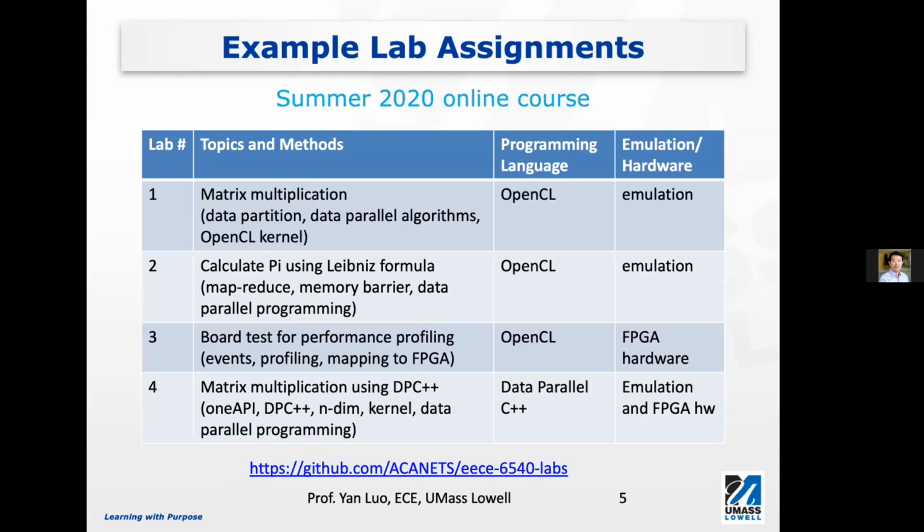Those 2 labs are run on Dev Cloud, but we do not require the students to run the real FPGA cards. They can do emulation. For the 3rd lab, students are required to build a board test program, which will do performance profiling using OpenCL events. And for this lab, they are required to generate the binary and load it into the FPGA cards.